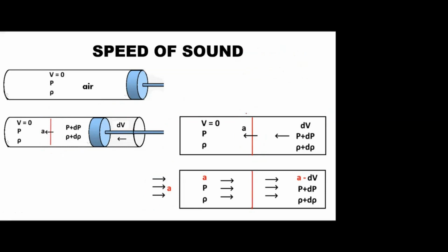So here it is, the moving wave in the real condition, but I don't want this moving wave. I need the stationary wave. Practically it is not possible, because if I stop moving the piston, it will vanish. So to apply the theoretical condition, I imagine another one. What is it? Imaginary control volume.